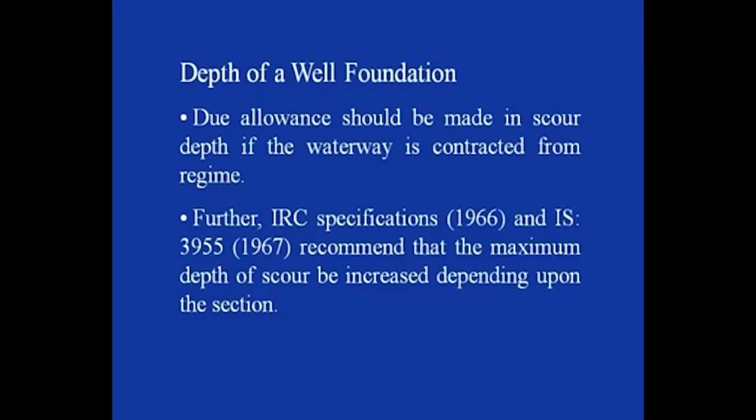Now due allowance should be made in scour depth if the waterway is contracted from the regime. Further, IRC specifications in 1966 and the IS code recommend that the maximum depth of scour be increased depending upon the section. The codes have given us the idea that, depending upon the type of section, one should increase the scour depth to a certain extent.